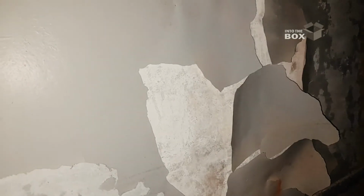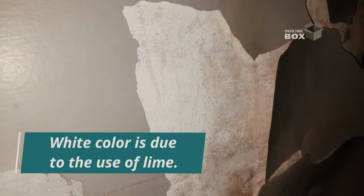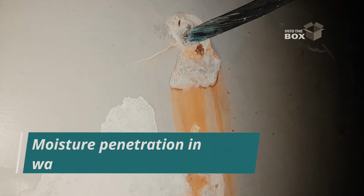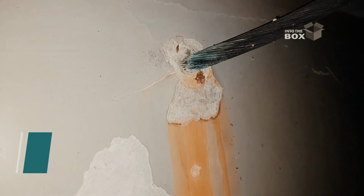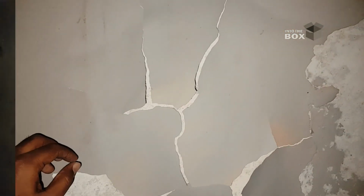This is also one more example of the same situation. This white color is indicative of the use of lime as the substrate. Secondly, as I was suggesting, the moisture has penetrated the wall. This is a live example of how the moisture has penetrated into the wall. There is a conductor over there, and when there is a water level at this location, the water might have seeped into the wall, which affected the paint surface and it cracked.